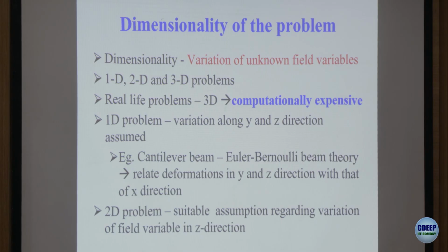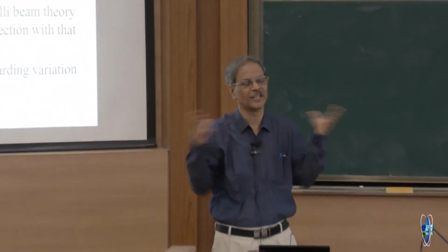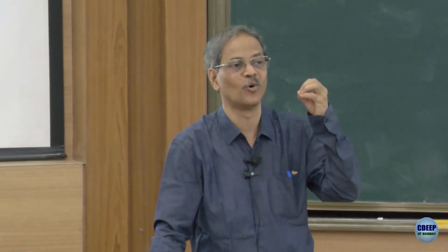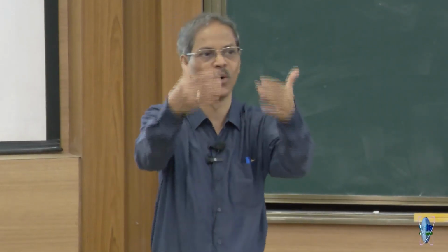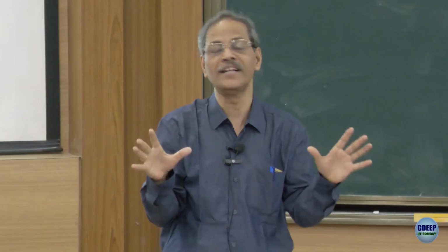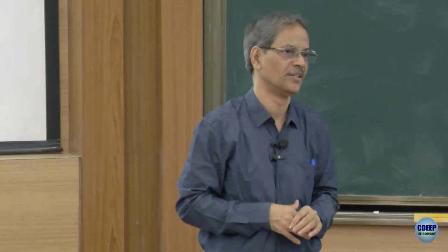Okay. So then you may not want to do a very detailed refined mesh with a large number of elements, but you may want to do with a coarser mesh, but try out various parameters and see if the change in the results is on expected lines. Then you get more confidence on your finite element model of the domain, boundary conditions, loading, material properties, all these things. Once you are confident, then you go ahead with full-fledged finite element analysis with refined mesh.